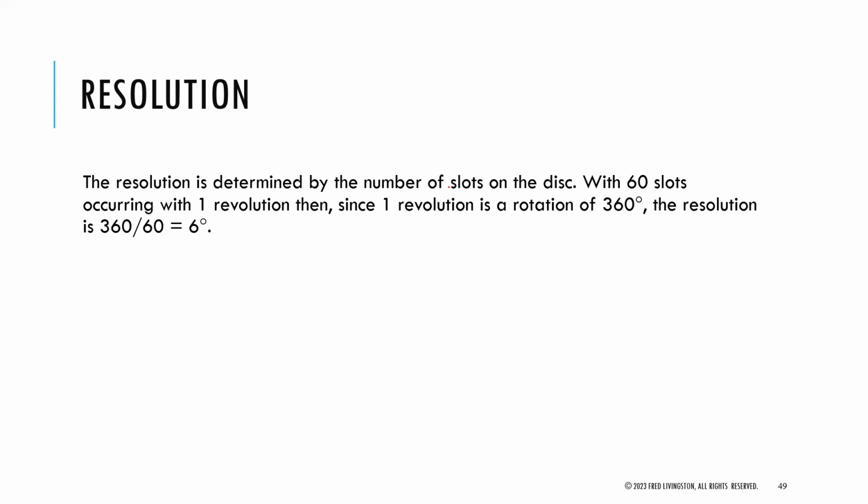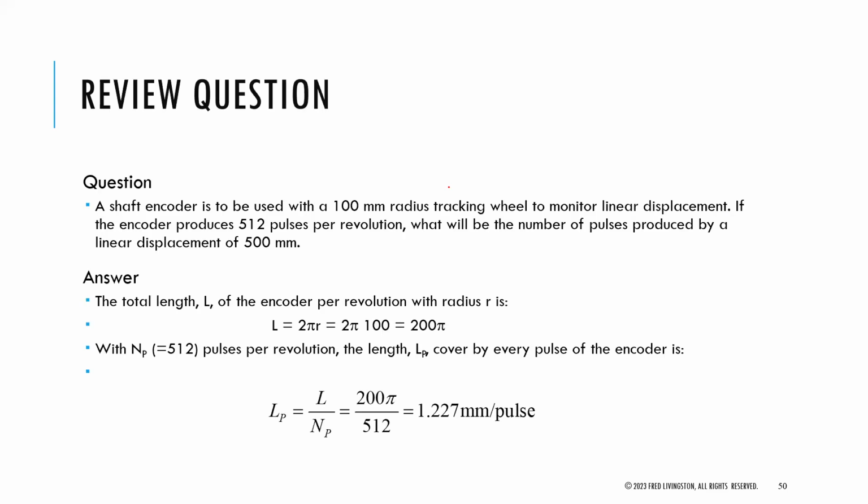And then if you're using the conveyor belt for your project, you may want to figure out what has an encoder in there. You may want to figure out the size of that encoder by looking at the number of teeth and the distance, and computing back the radius. In this case, we're just computing the distance per pulse. So review this for your exam. I think that was one of the questions on that practice exam.